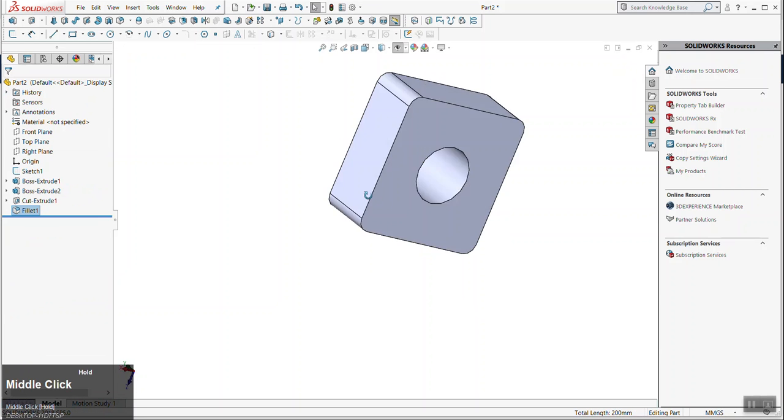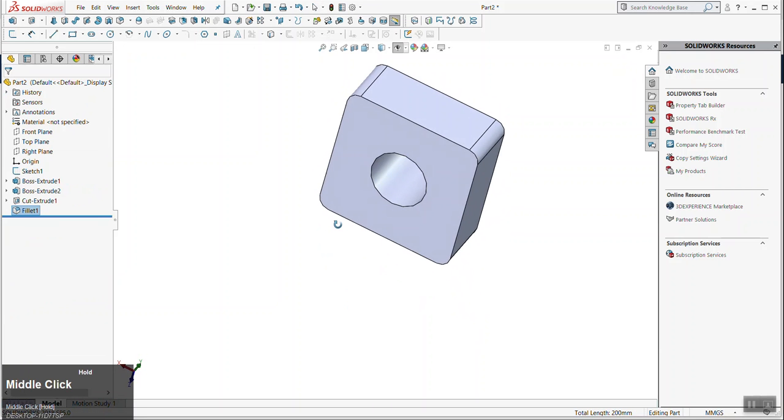Yeah, for the shape. So a shell, what the shell does, who wants to try and verbalize what a shell does? Yep. Great. I would say the key there is that it hollows it out, but no, that was very well said. Both are important. It hollows it out to an even thickness. It's a very useful tool because most objects that exist in real life that we interact with, it's very rare that it is a solid body.